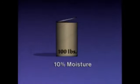An analytical variable that's similar to humidity is moisture. Moisture is a measure of the amount of water absorbed by a solid material. Moisture can be measured in ounces of water per pound of material, but it's more often measured as a percent of total weight. For example, a moisture measurement of 10% means that 10% of the weight of a material is attributed to water. So if there are 100 pounds of material, there are 10 pounds of water.